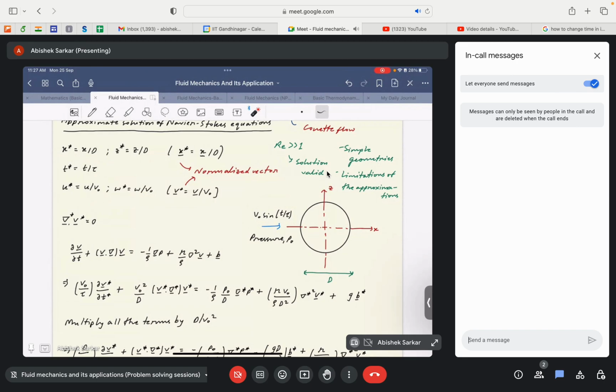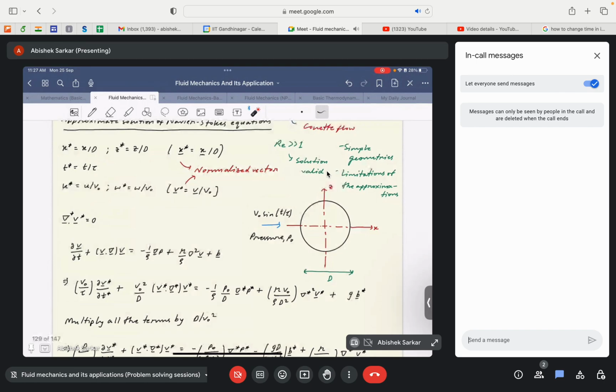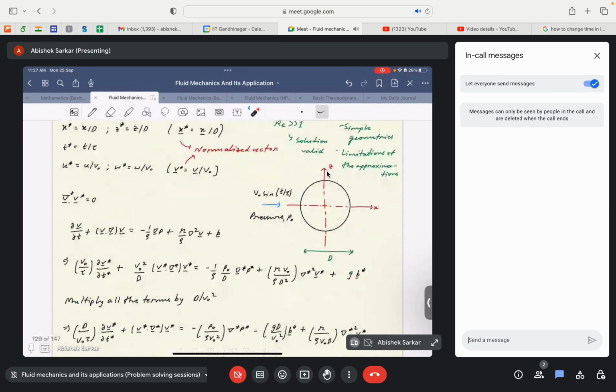The non-dimensional form of the continuity equation is very simple. It's basically the same, as it is homogeneous and only contains single terms. All the non-dimensional parameters that come after non-dimensionalizing the governing equation can be taken as a constant and transferred to the right hand side. So the form of the continuity equation remains exactly the same, but now the velocity and the nabla operator are non-dimensional.